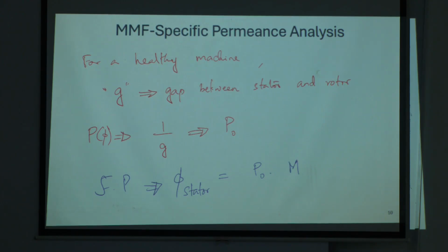So there is a constant times cos of (N P phi plus or minus omega t) in the stator frame of reference. So MMF into permeance, that's all I have mathematically. And of course this will change depending upon the order of harmonic you are considering.